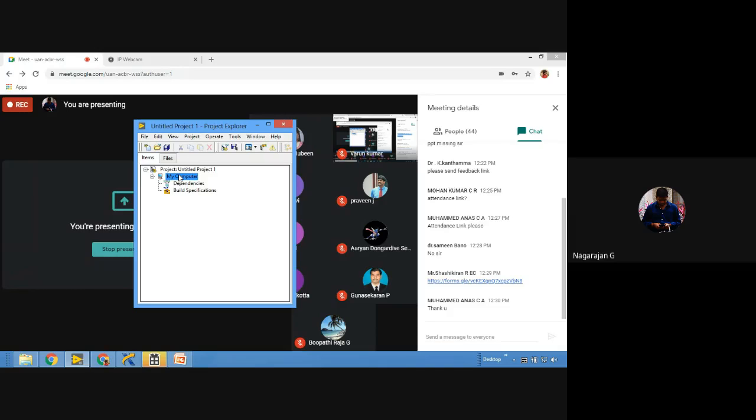We have to write a code and then dump it inside the respective NI myRIO hardware. In order to do that, you first need to add the target under this project. Right now only my computer is added.